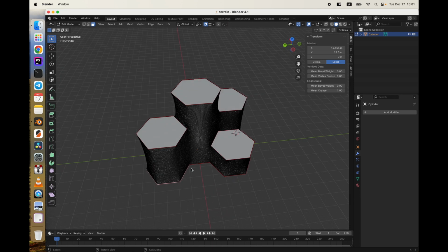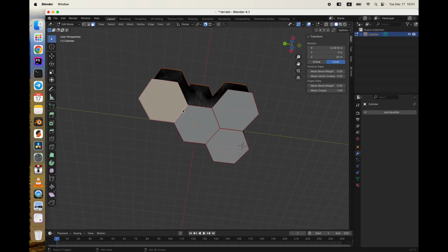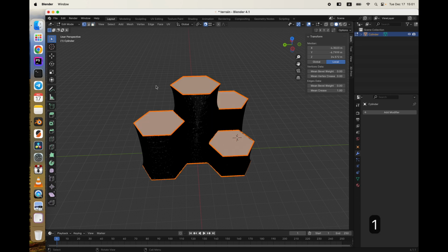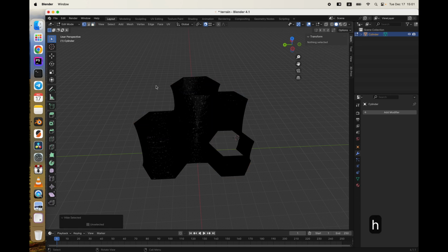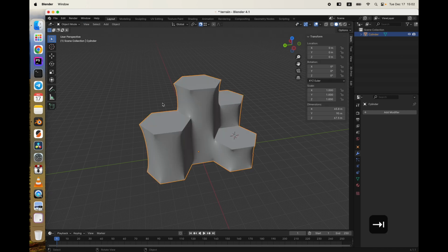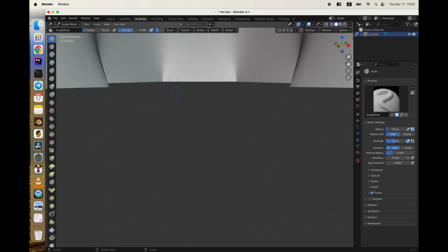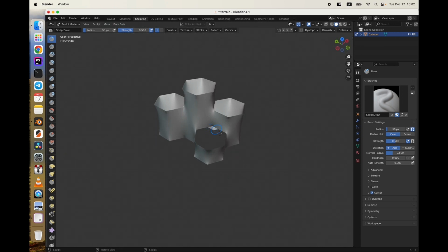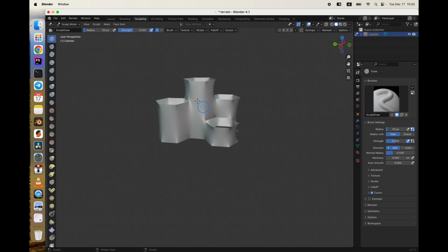Now select all horizontal faces again. This, and all of that. Go to the vertex mode 1 and press H to hide these faces. Exit edit mode and press the Sculpting tab. Let's zoom out. So, why did we hide our faces? Because when we edit our surfaces here, these faces, the horizontal ones, would not be available for editing and they will stay the same.